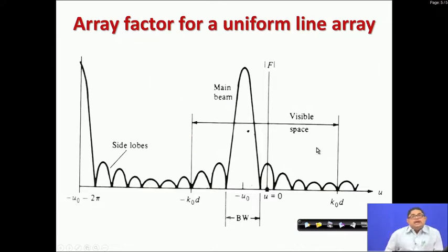So, this is something like the sinc function, but the only difference is that this is a periodic function, sinc is not a periodic function. So, this behaves much like our normal sinc function, which is sin u by u, but here this is sin (n plus 1)/2 u by sin u. So, this is a different function, this is the heart of array antenna study, this is called the array function.